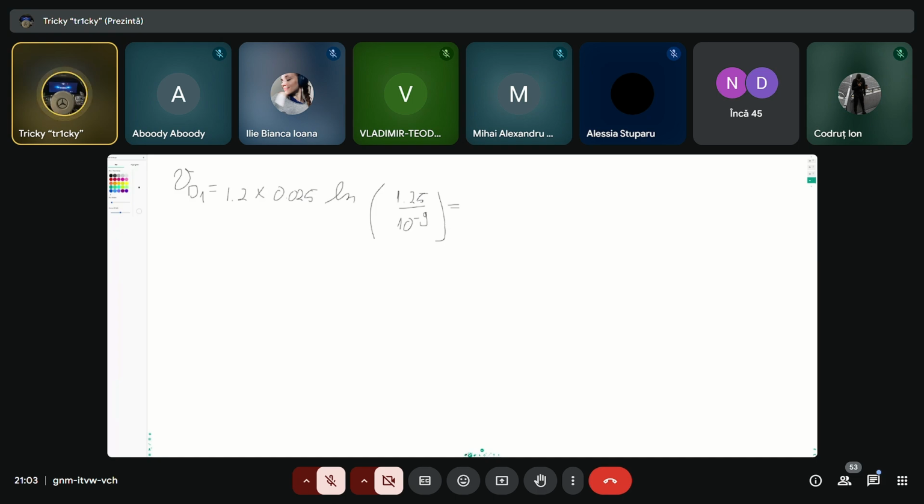So, your colleague is saying this for this circuit number 3, it's 1 picoampere instead of 10 picoamperes. Not that big of a difference, so it's fine. And for this, we will get the value 0.628 volts, which is also equal to VD2 because they have the same current.